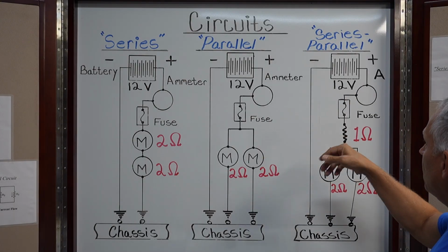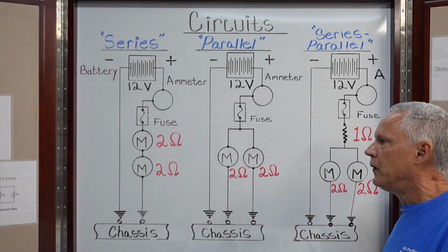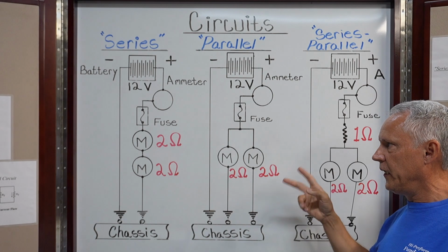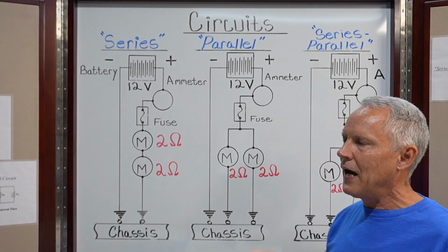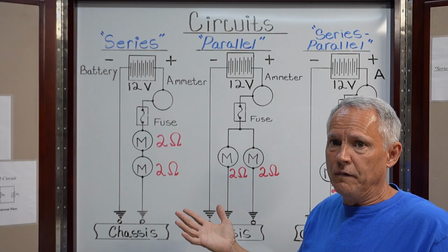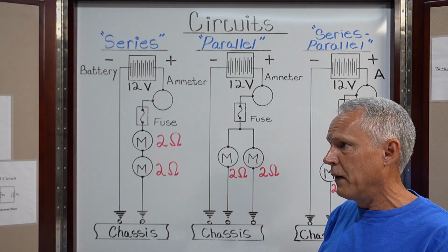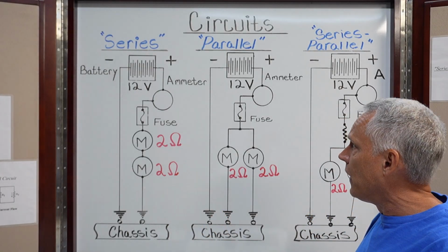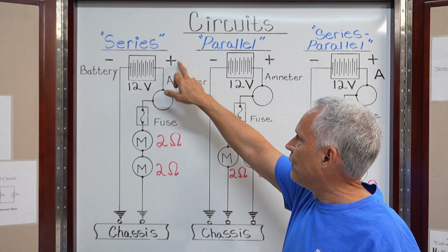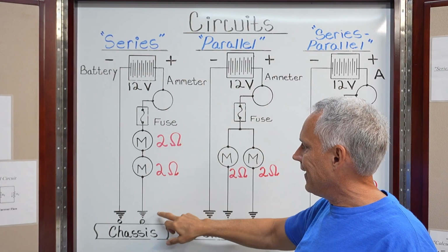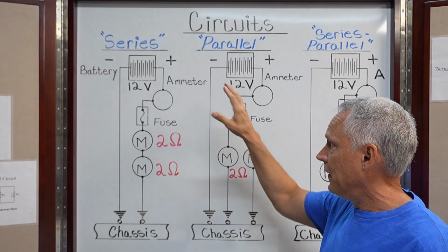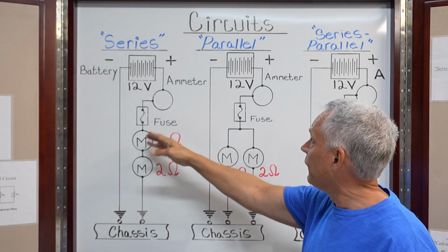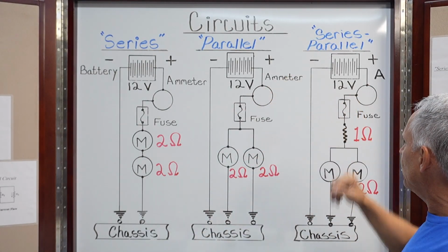Series circuit, parallel circuit, series parallel circuit. Right? This is much more indicative of what you're going to see in a wiring diagram, okay? And in most cases, I can't say every case because I can't say I've ever seen every single wiring diagram made by every manufacturer on the planet, but it's very common that you'll find the positive at the top of the page and a negative at the bottom of the page. Like I said, I can't say that they're all done that way, but that is very common, all right? So series, parallel, series parallel.